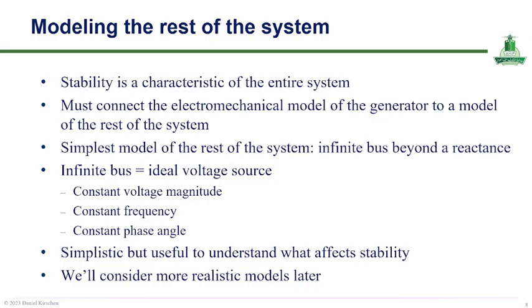Therefore, the generator's electromechanical model must be connected to a representation of the surrounding network. The simplest approach is to model the rest of the system as an infinite bus behind reactance. The infinite bus acts as an ideal voltage source with constant voltage magnitude, frequency, and phase angle.